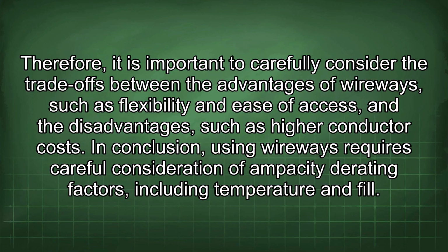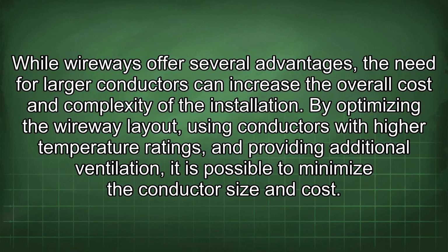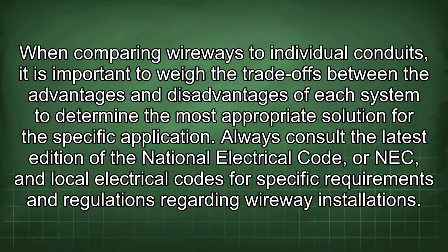In conclusion, using wireways requires careful consideration of ampacity derating factors, including temperature and fill. While wireways offer several advantages, the need for larger conductors can increase the overall cost and complexity of the installation. By optimizing the wireway layout, using conductors with higher temperature ratings, and providing additional ventilation, it is possible to minimize the conductor size and cost. When comparing wireways to individual conduits, it is important to weigh the trade-offs between the advantages and disadvantages of each system to determine the most appropriate solution for the specific application.